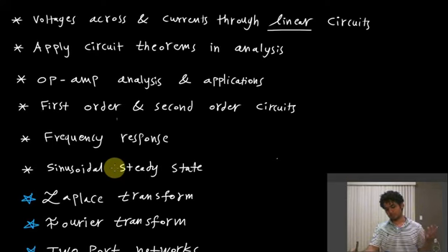If you suddenly turn the switch on or off, you're disrupting that current. And so to be able to maintain a certain amount of current, the electromagnetic laws that govern the behavior of an inductor require creating a very sudden spike in voltage, something called kickback. It's going to create a spike in voltage and basically damage particular parts of your circuit. That's why, for example,